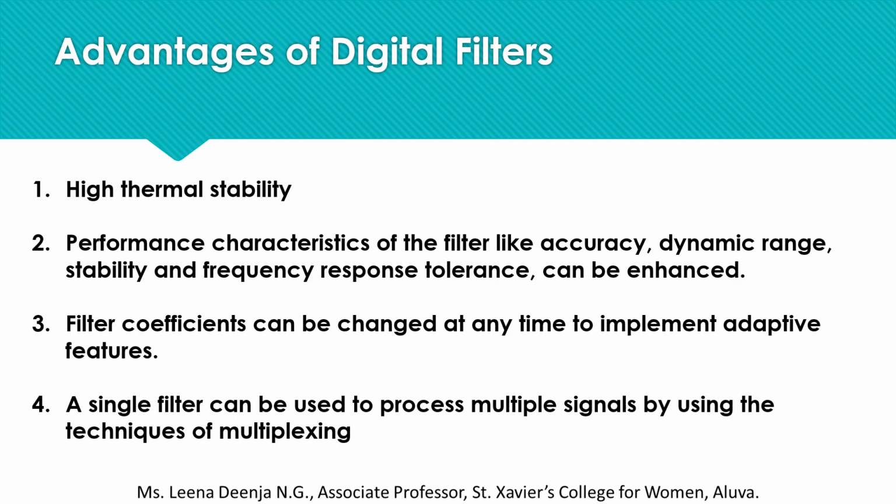Second advantage is that in digital filters, the precision of the filter depends on the length or size of the registers used to store the filter coefficients. Hence, by increasing the register bit length, the performance characteristics of the filter like accuracy, dynamic range, stability and frequency response tolerance can be enhanced.